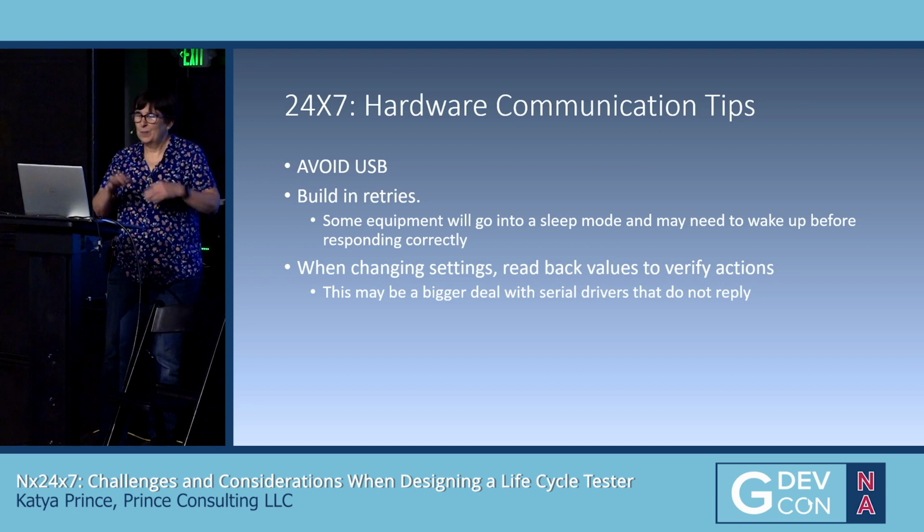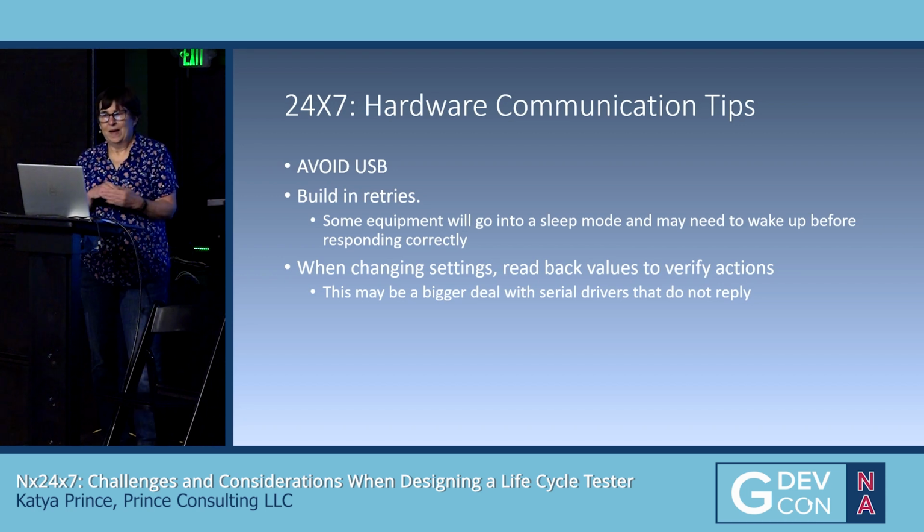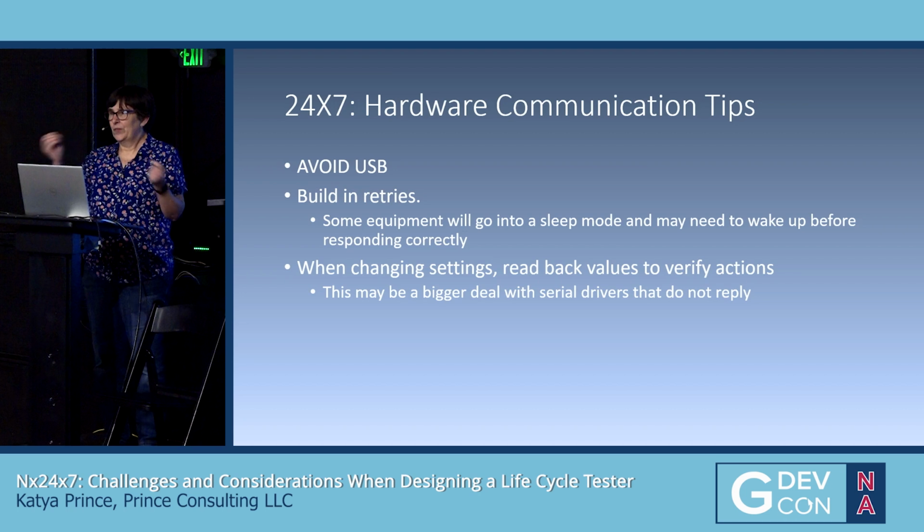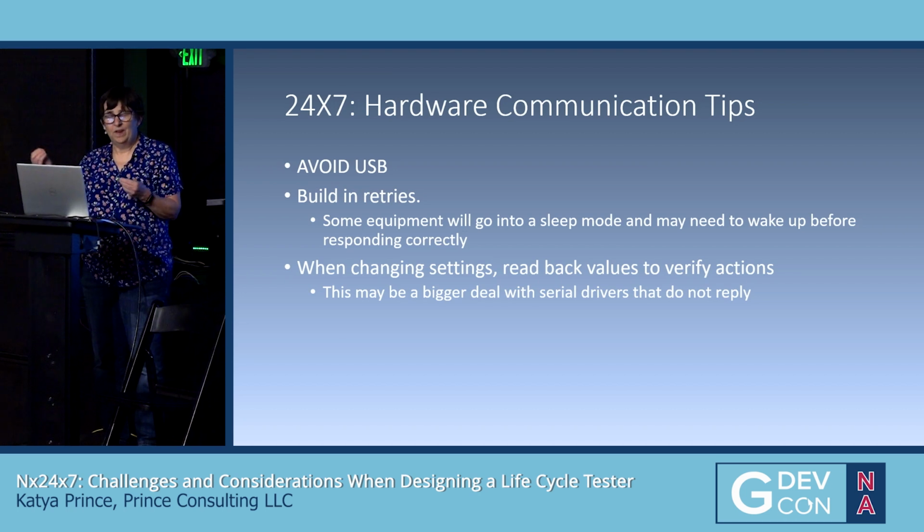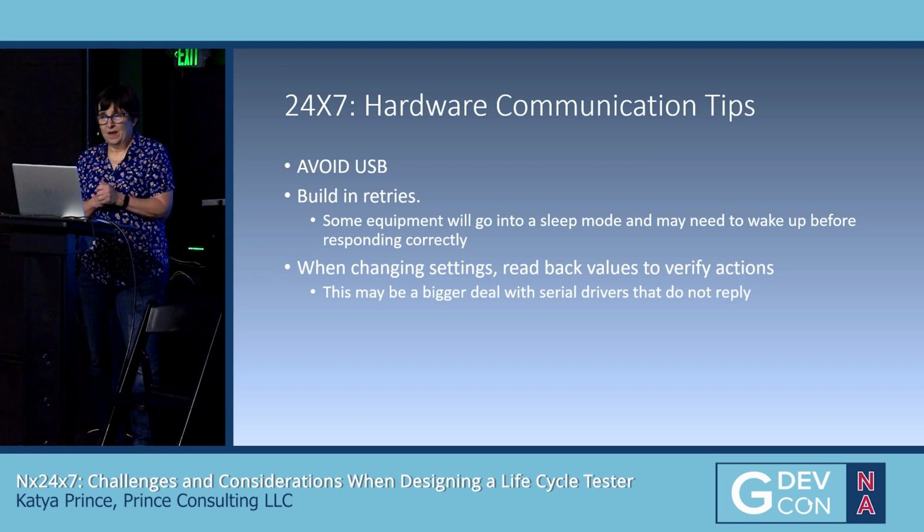Again, I'm reiterating some of the stuff, but don't assume that the first time you can't talk to the hardware that there's a problem. Try to talk to it 2 or 3 times. Put a little delay in. And some equipment, like I said up here, if you're not talking to it frequently, like a power supply, some of these instruments, especially the older ones, go into a sleep mode, and you have to ping it a couple of times before it wakes up.